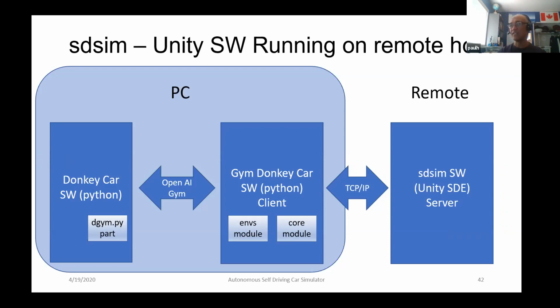What that means is your inference of your images and the steering and throttle that you're passing back has a delay in it. And that can have a material impact on how well you are responding to the images you see and the control signals that you're sending back to your model. So yeah, 100 milliseconds: 20 frames a second is 50 milliseconds per frame. That's 2 frames. So you're actually predicting 2 frames behind where you are on the track. Right. Good point, Ed. I didn't even think of it that way, but that's a really good point.